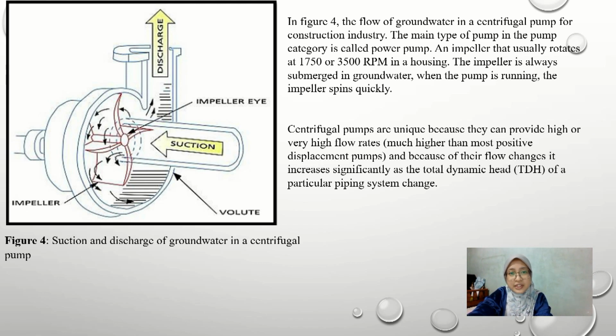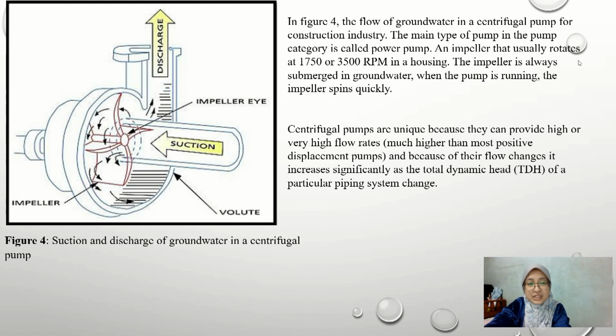Centrifugal pumps are unique because they can provide high or very high flow rates, much higher than most positive displacement pumps, and because their flow changes significantly as the total dynamic head of a particular piping system changes. Therefore, centrifugal pumps can cover a very wide range of liquids. The application of pumps in the dewatering process of construction sites.